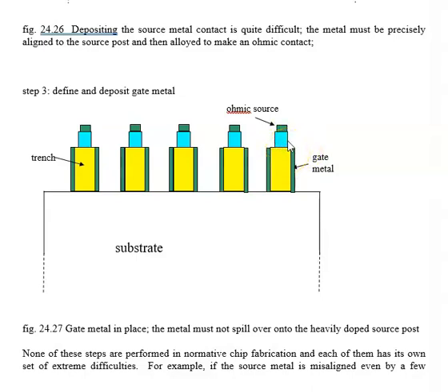This distance here is about 0.3 to 0.4 microns. The ohmic contact will be somewhat less than that, say a quarter micron. So I have to align a quarter micron photolithography to a 0.4 micron, with no misalignment allowed whatsoever. That is incredibly difficult to do. And then the other thing is I've got to somehow stick this gate metal onto